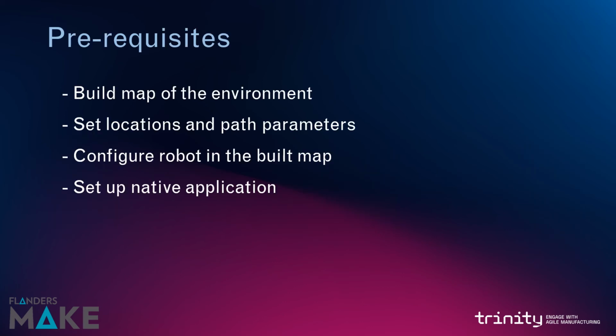This slide discusses the prerequisites which are required for the mobile manipulator to operate autonomously. For autonomous operation, KUKA navigation solution software acquires all the data from the safety laser scanners and wheel sensors and uses them to create a corresponding map of the surroundings by means of the SLAM method.